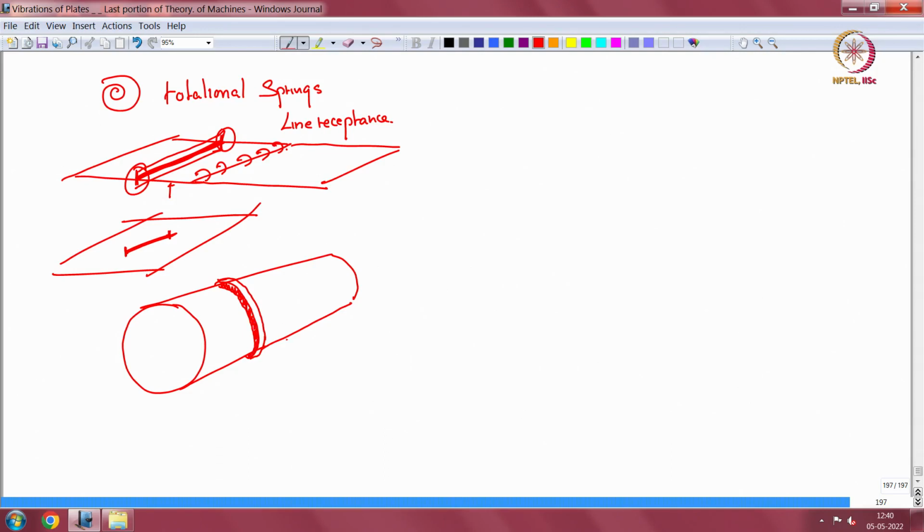Then the n that the shell goes through, either cos n theta or sin n theta, must be the same for the ring. If that is so, you can do a connection between the two and you can stiffen the shell. So, we will look at stiffening of the shell in the next class, how to stiffen a shell using a ring, using the receptance method.